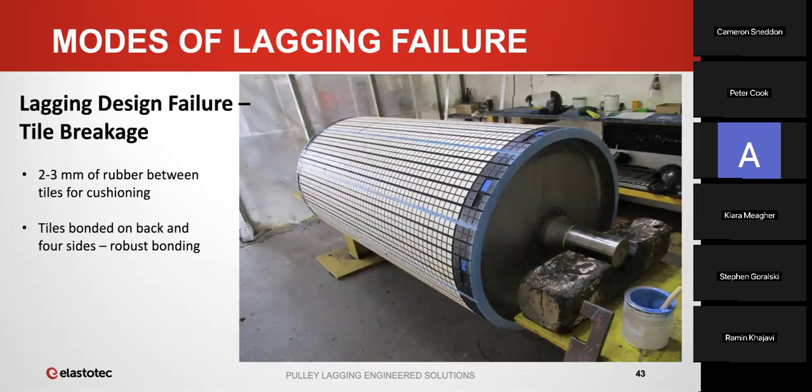The third thing that you can do is put a cushion of rubber between the tiles. You will have seen that there are ceramic, and I'm talking now about the full ceramic, the 80% ceramic, versions where the tiles are touching each other. The problem with that design is that when you get material caught in between the belt and the lagging, it point loads onto the tiles, and if the tiles are touching each other, there's basically nowhere for things to move.